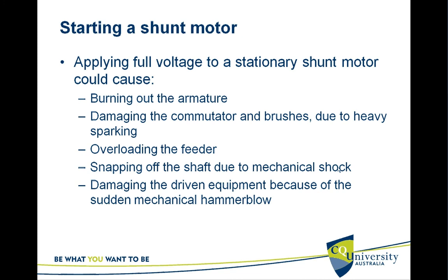Damaging the commutator and brushes due to heavy sparking, overloading the feeder, snapping off the shaft due to mechanical shock. The sudden shock can even snap off the rotor shaft. Damaging the driven equipment because of the sudden mechanical hammer blow. So if the motor shaft is connected to some kind of a load, that load can also get affected.